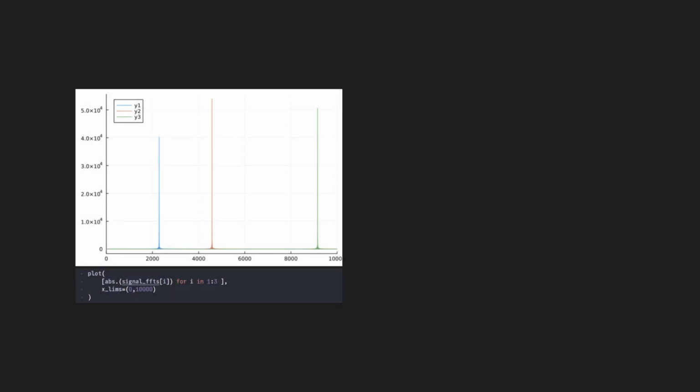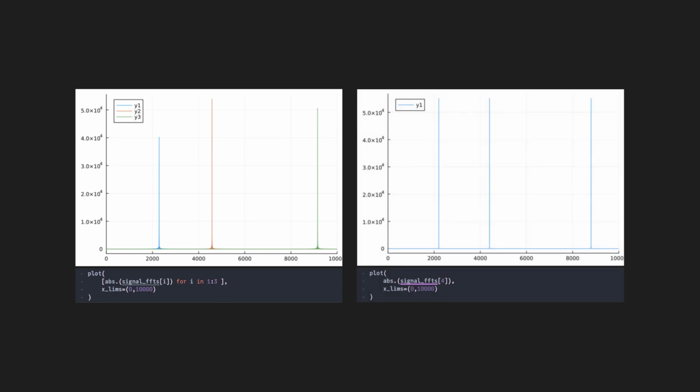If we plot all these three in the same graph and simultaneously take the fast Fourier transform of the fourth combined wave, we can see that the same frequencies are being discerned. However, in the FFT of the combined wave, they're all at the same amplitude because all of the notes are played at the same volume. Now that we can discern the separate frequencies, we can filter them. We can boost the volume of some parts and reduce the volume of others and apply equalization as we feel.